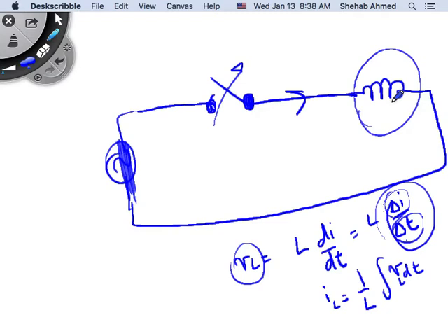Last class we said that the breakdown voltage of air is 30 kilovolts per centimeter. So if you have two contacts that are 1 centimeter apart, and you have voltage across them that's 30 kilovolts, you break down the air and you cause an arc. If I'm operating a power system at 400 kilovolts, and these contacts were closed, now you're going to open them. They're a lot closer than 1 centimeter. You will see a huge arc develop because you broke down the air. The contacts were stuck to each other, now you're opening it up, and you will see a huge arc develop.